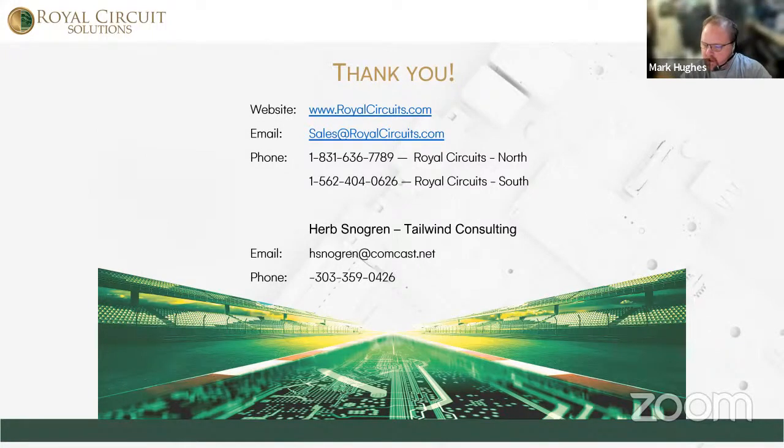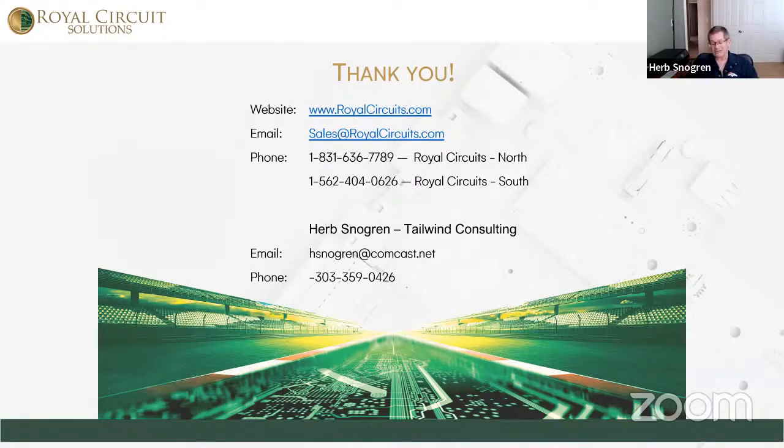William would like to know, are there any resources to calculate current carrying capability of these Ultra-HDI traces? Will conventional calculators be accurate in this range? And I can take this one if you can't, Herb. Yeah, IPC has some conductor width calculators, and it's based on temperature rise.